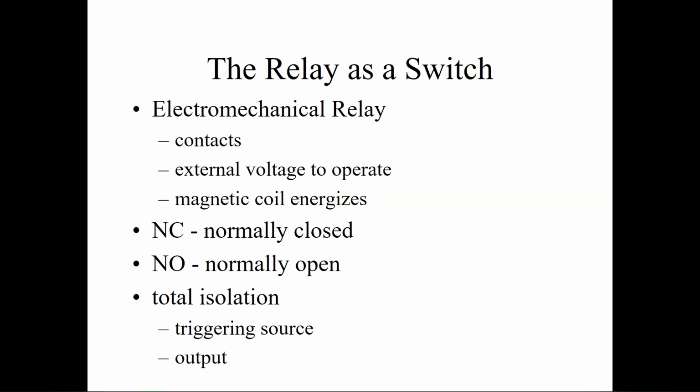Well, normally open means that the circuit will not close until told to do otherwise. Normally closed means that the circuit will stay running until told to do otherwise. Does that make sense? Doesn't it also mean if they're de-energized, they'll go back to those resting states? Yes. Basically, these don't change states unless they're forced to.